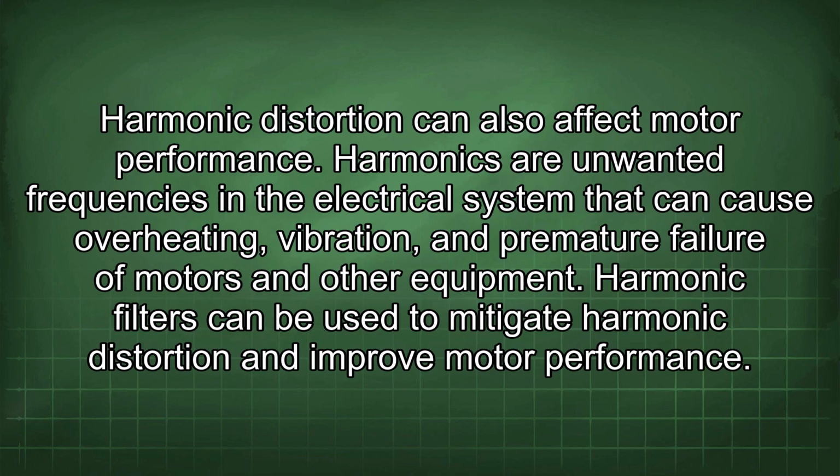Harmonic distortion can also affect motor performance. Harmonics are unwanted frequencies in the electrical system that can cause overheating, vibration, and premature failure of motors and other equipment. Harmonic filters can be used to mitigate harmonic distortion and improve motor performance.